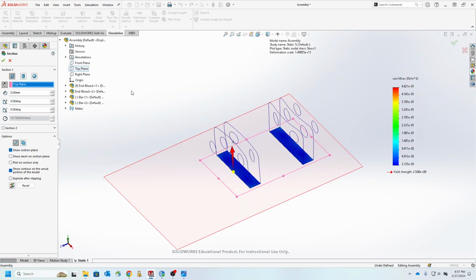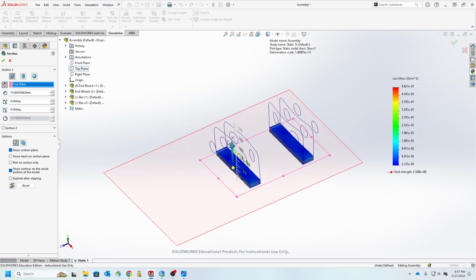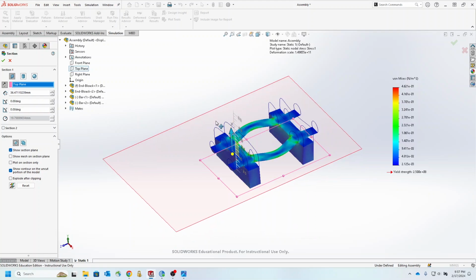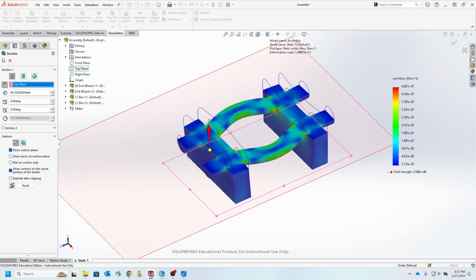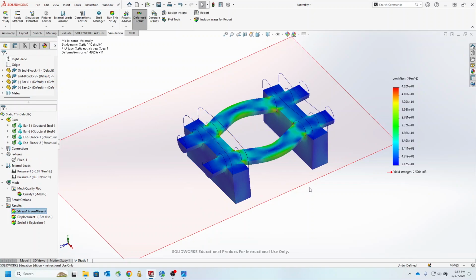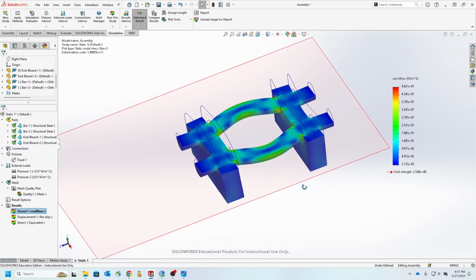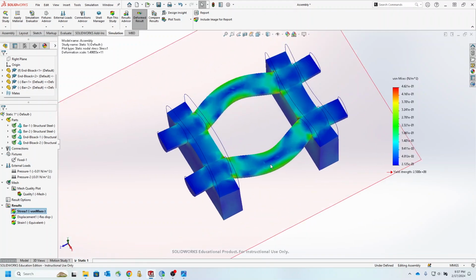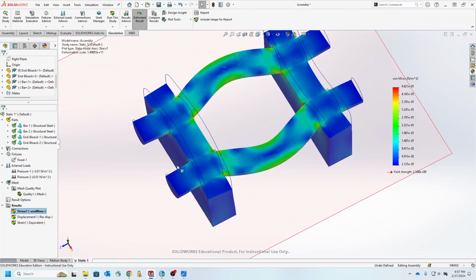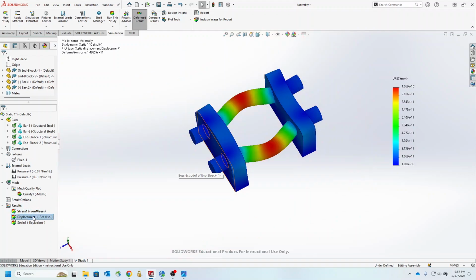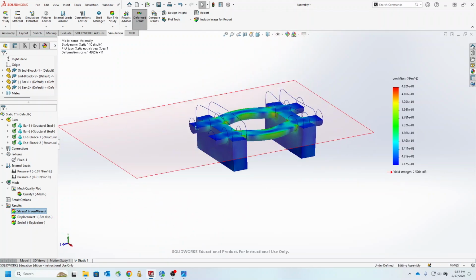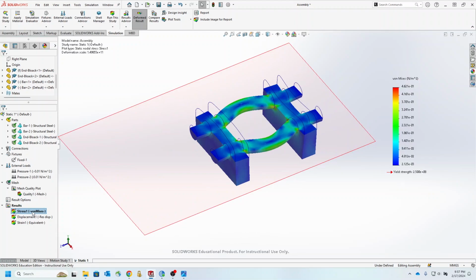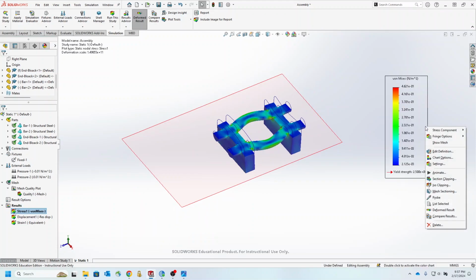There you go. And now that gives you an arrow that you can actually pull up, and you see at every point, and this is almost half of the bar. And if I hit OK to stay there, I can see how the stresses have been formed here. Or if I wanted to keep this and go to the displacement, it would be pretty much the same. I have to define the same, but it stays here. And that is essentially how you can create a section out of it.